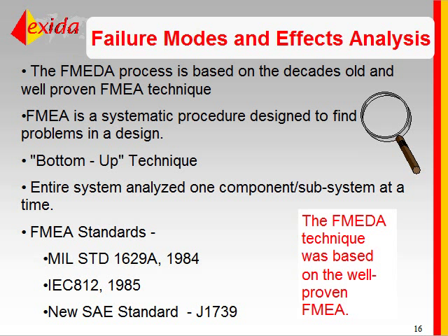Many of you who have been around the field of reliability engineering know that FMEAs were developed in the mid-60s. The history of reliability engineering that I read says they were developed during the Minuteman rocket program in the United States, and it turned out to be an effective method to find design defects. Over the last 40 to 50 years, this method has been expanded and is pervasive in many industries. It's a bottom-up technique where an entire system is analyzed one component at a time.